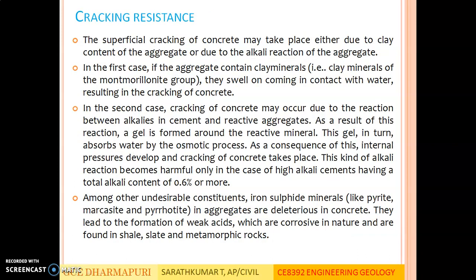The final property is cracking resistance. The superficial cracking of concrete may take place either due to clay content of the aggregate or due to the alkali reaction of the aggregate. In the first case, if the aggregate contains clay minerals of the montmorillonite group, they swell on coming in contact with water, resulting in the cracking of concrete.